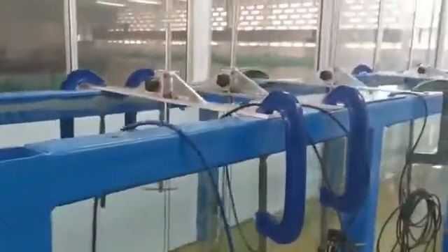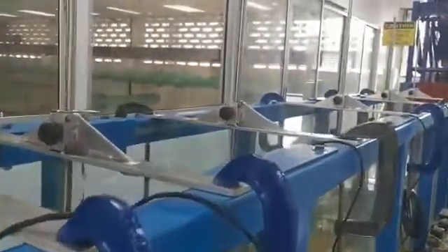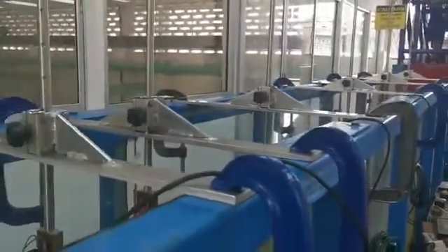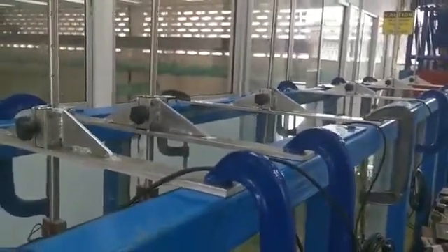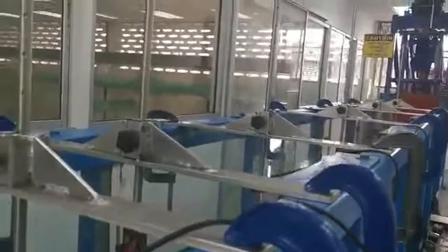We also have some wave gauges set up here. We have 6 gauges: 1, 2, 3, 4, 5, 6. As we could look inside, they are in the water column. When we set up these wave gauges, they have to be calibrated so that you will be able to know the wave height.